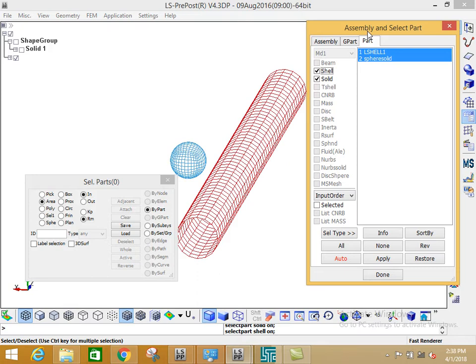Okay, let's say this whiteboard is solid, right? But if I want to model it in DYNA to make it simple, to make the simulation fast, I can just tell the software it is shell element, meaning I just model it like this. Then I tell the software that this shell has a thickness of maybe 5 mm, 10 mm.